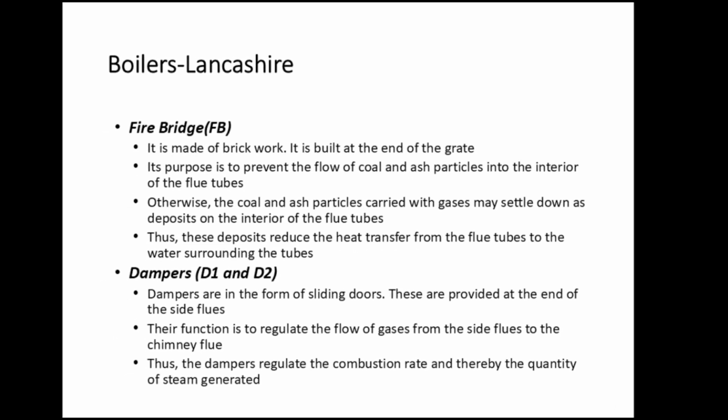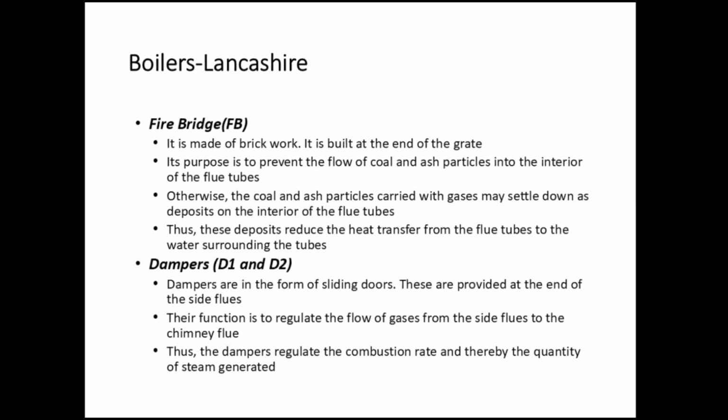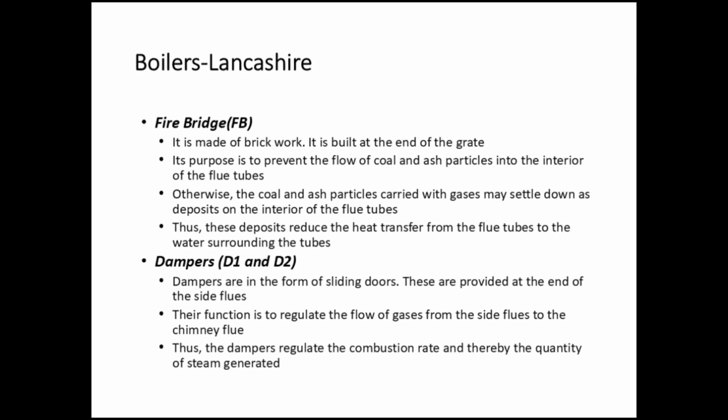Boilers, Lancashire, fire bridge, FB. It is made of brickwork. It is built at the end of the grate. Its purpose is to prevent the flow of coal and ash particles into the interior of the flue tubes. Otherwise, the coal and ash particles carried with gases may settle down as deposits on the interior of the flue tubes. Thus, these deposits reduce the heat transfer from the flue tubes to the water surrounding the tubes.